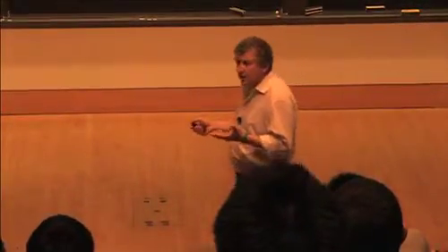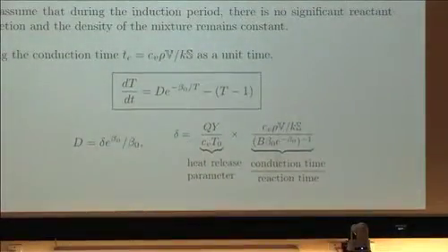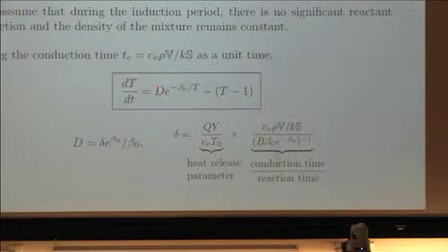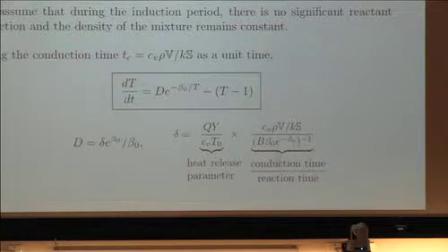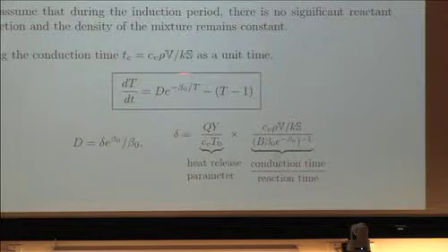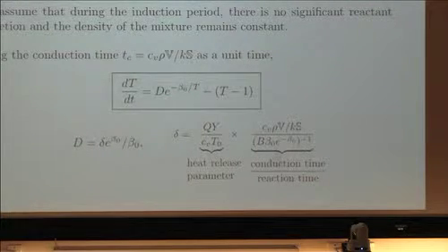So the first thing that you ask is, are there any equilibrium solutions? Are there any steady solutions to this problem? Steady solution means that the temperature does not change in time anymore, right? So if there is a steady solution, it's going to be a balance between the heat produced by chemical reaction and the heat that is lost through the walls. And so it's going to be a solution of this algebraic equation, which is the right-hand side of the equation equal to 0. Well, to solve this algebraic equation is complicated because it's also a transcendental equation. But it can be done by graphical method.